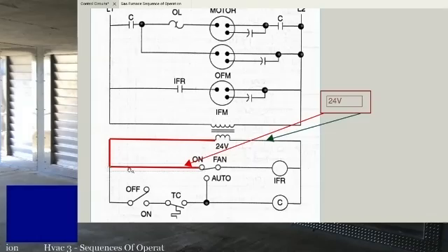It goes in and then it keeps going from there. You go down. This is basically your off-on-cooling switch, and then that goes in. What we're showing over here is to your fan. You just think about it as a separate switch. Fan is your common terminal on this two pole relay, and you either have it set to on or auto, and we'll follow the circuit in a minute.